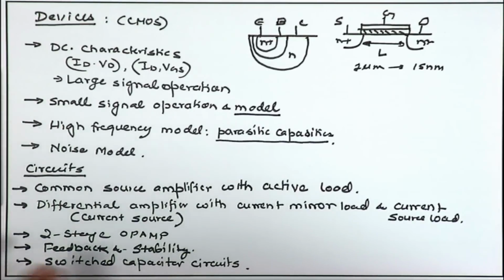It basically involves a combination of MOSFET switches and capacitors integrated along with operational amplifiers to give us some interesting functionality for amplification, for filtering, A to D conversion and so on. So, the switched capacitor circuits are going to be very fundamental and essential in coming up to the higher level. They are going to act like a link between the circuit level components we discussed and their application in building the functional units, namely the amplifiers, filters and the ADC. So, we will have some discussion on the switched capacitor circuit concepts as well.